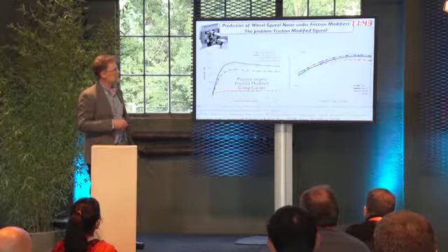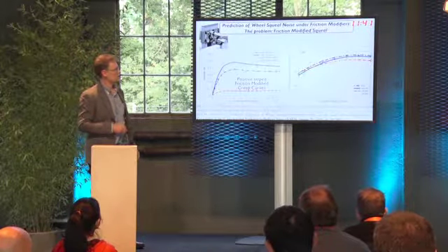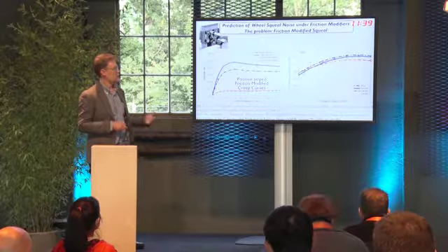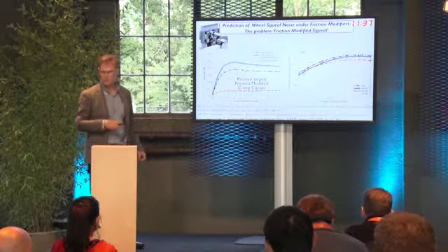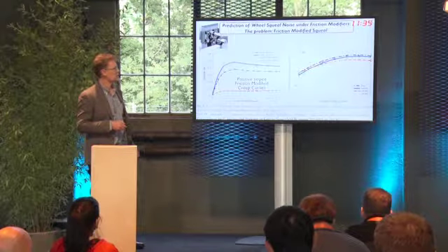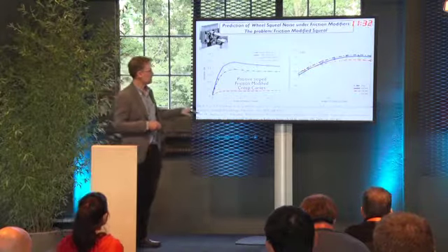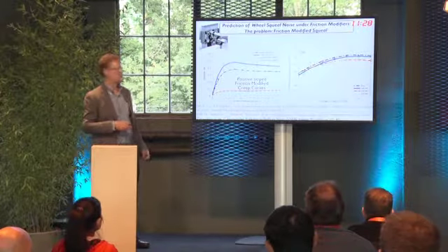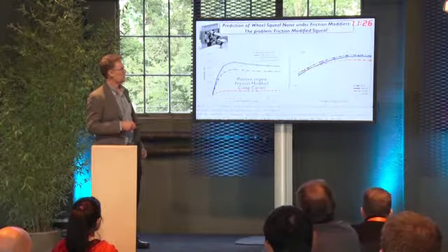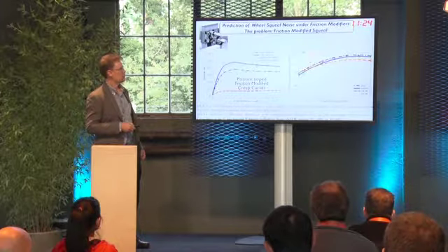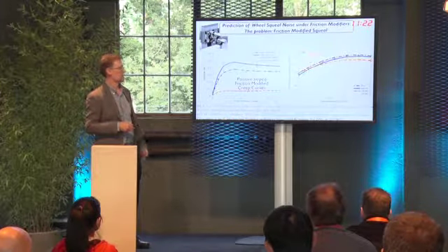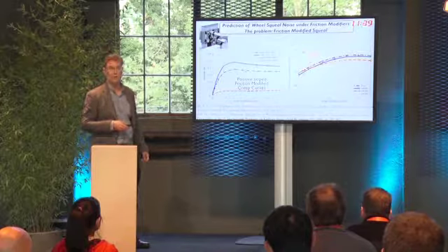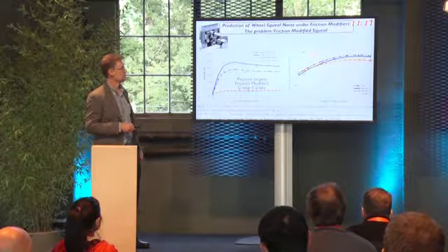So here's an example of our test rig where we tested under dry, water-based friction modification and oil-based conditions, and even though the lateral creep curves had a positive or non-negative slope, we still got squeal. The squeal is indicated by typically above 100 dB measured on the test rig.